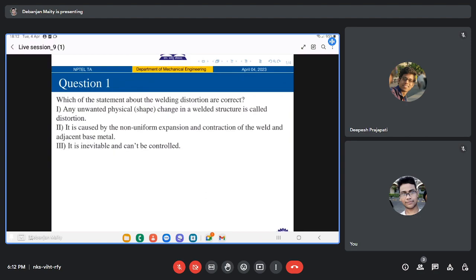Can you tell me some examples where stress can be generated by a phase change? Any guess? A well-known example is the crushing of a wood or fiberglass hulled boat by ice formed in a lake, river or canal. The specific volume of water increases with change from liquid to solid, right?